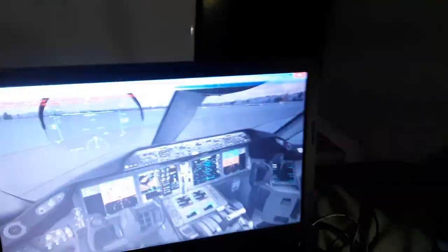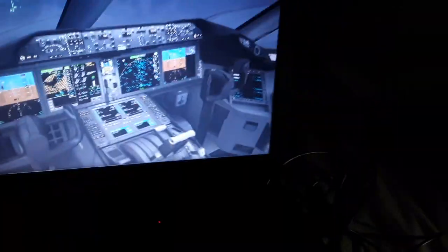Now I will show you the primary flight display, autopilot, and flight director system panel setup. I will set up the flight management computer first. I'll set up the flight plan for this flight. I will input all the data of the aircraft for this flight: the takeoff gross weight, that includes the passengers plus the cargo plus the fuel on board, where the fuel is stored in the left and the right wing